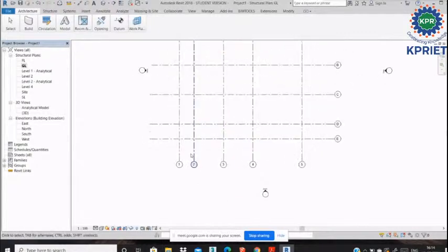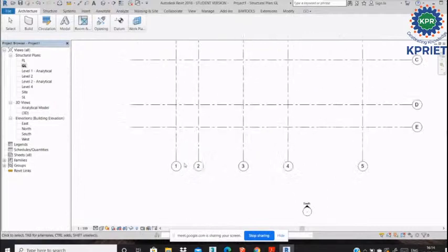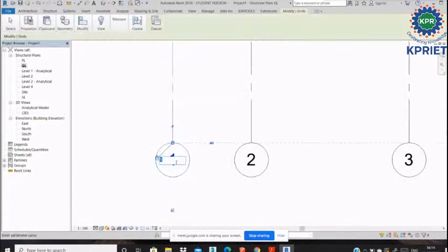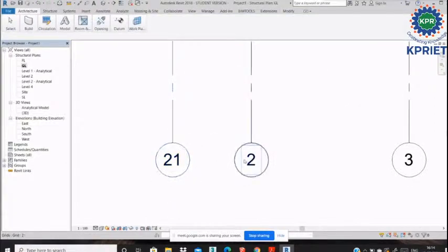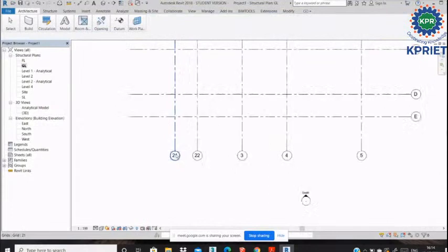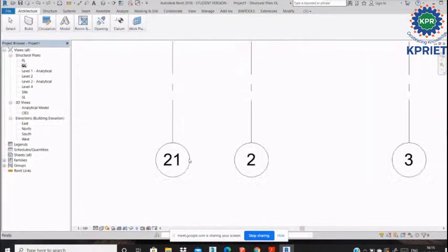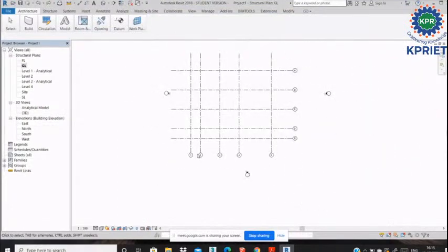Right. Simply go to draw the grid lines. Simply double click, you change the name to 20, right, 21, 22. Simply click this 22. How to understand how to change the grid line names, right? Fine. Now the grid line itself is simply created.